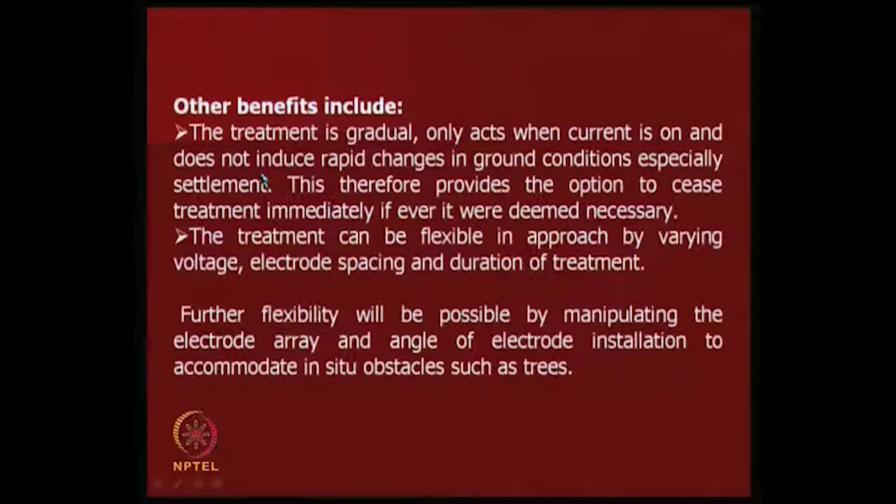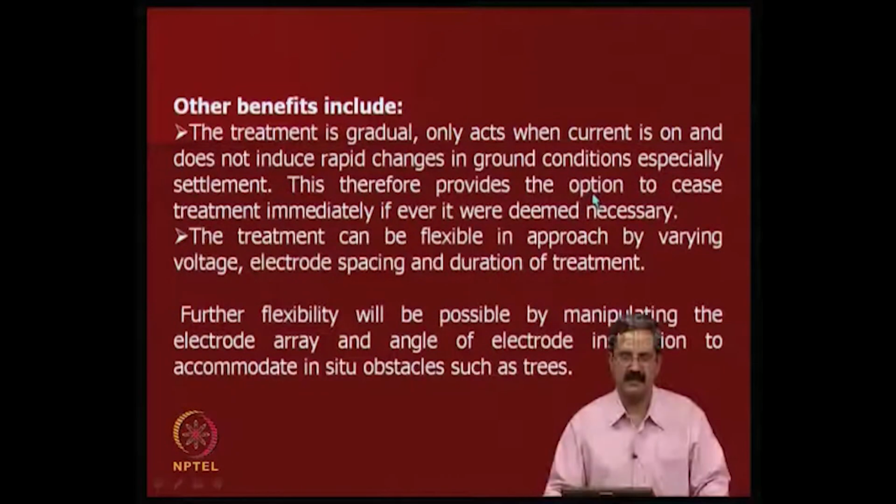The other important technical benefit is about settlements. Removal of water is there, but it is not accompanied by changes in effective stress. So, the changes in effective stress are not leading to any settlements.